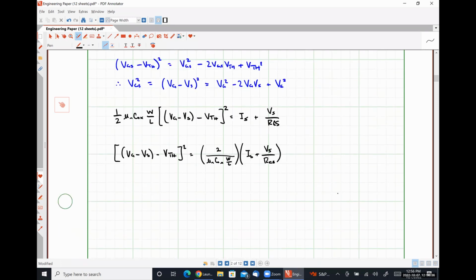I'm just going to write this down and we're going to talk about stuff. We'll figure it out on the fly. So what I have written down here, I can see on the right-hand side that I've effectively just distributed that fraction, which is not a particularly big deal. But on the left-hand side, I'm having a little bit of difficulty following my work. The goal here is for us to figure out a mathematical expression that allows us to solve for VS, because VG is well defined because of the voltage divider. VD is well defined because it's literally tied exactly to the power supply voltage.